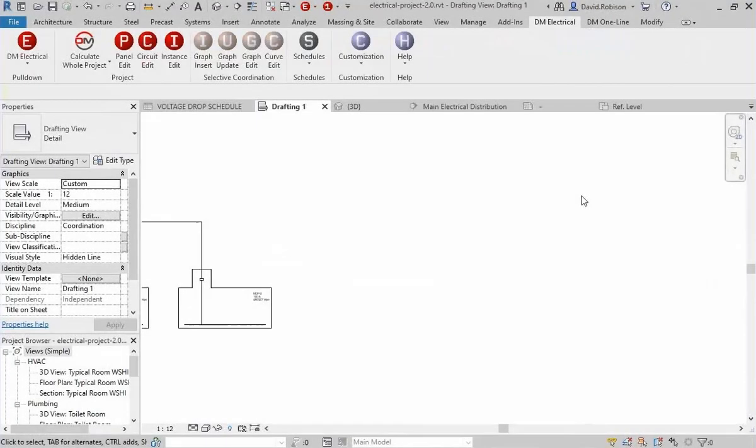The other probably flagship feature that we have are breaker curves, so that you can do selective coordination and arc flash trip times in Revit. Previously, we had arc flash calculations, but to get your trip times, you had to find the curve yourself and manually look up the trip time. It worked. It's not as slick as other programs. And we couldn't do anything with selective coordination. So with this release, we've added breaker curves so you can actually do a selective coordination, and so that we can calculate those trip times as well. So let's go ahead and take a look at that.